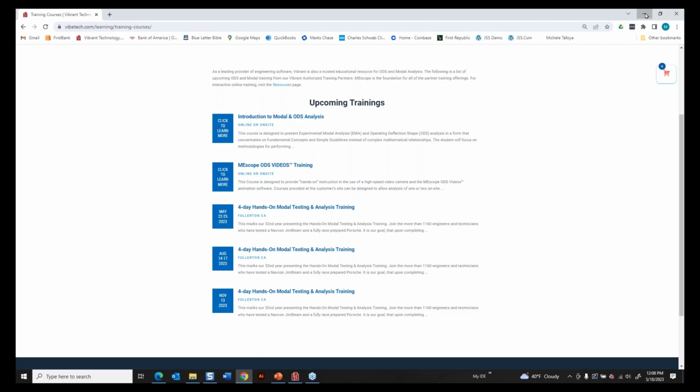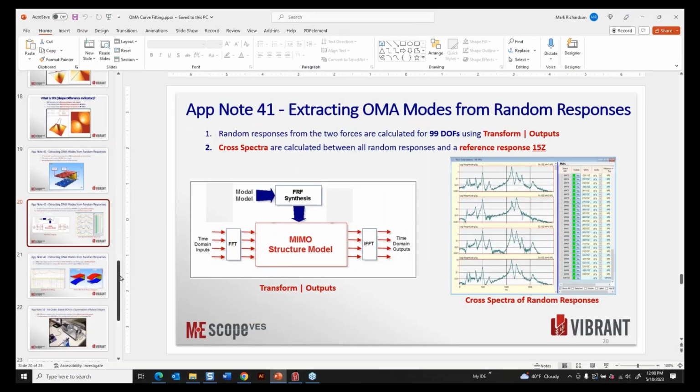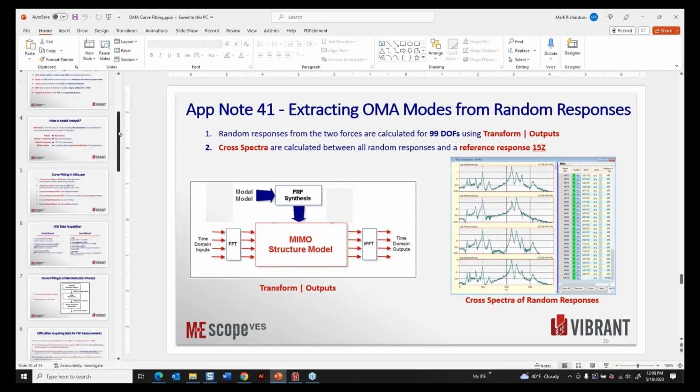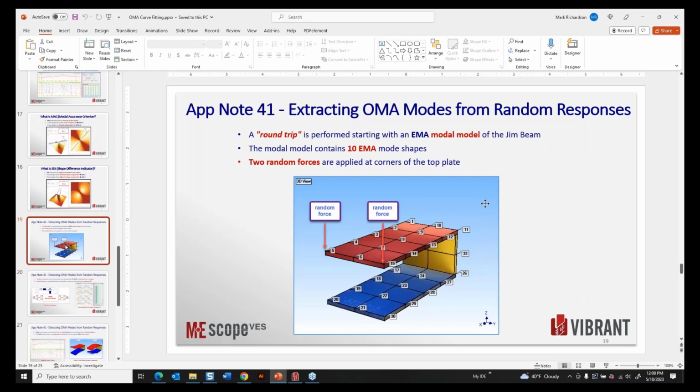So let me put that down, and we'll just go back and look at the gym beam here real quickly. So that's one, and I'm giving you a little preamble here as to what we might cover in the next webinar. So here's a model of the real gym beam. I got one here in the office, and those 3 plates are attached by cap screws. So probably 10 years ago, we demonstrated the ability to detect how much torsion was on those cap screws, just using modal frequencies.